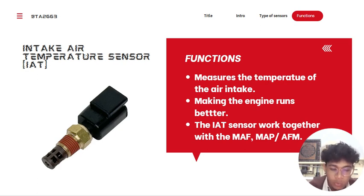The IAT sensor works together with the MAF, the MAP, or the AFM to give the ECU a more complete picture of the air coming into the engine, which helps reduce emissions and improve power and efficiency. Just like almost all the other temperature sensors in the car, the IAT sensor is a thermistor, meaning that its electrical resistance is going to change in response to changes in its temperature.